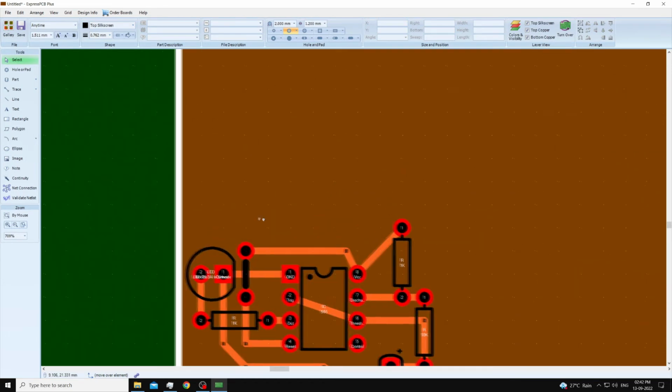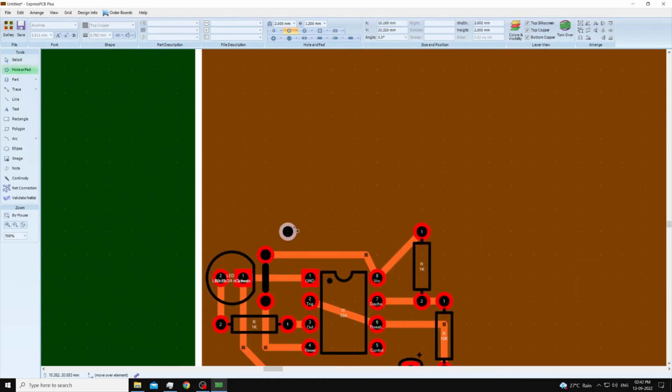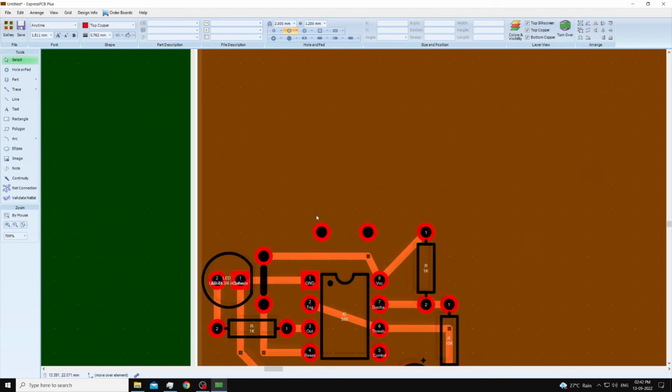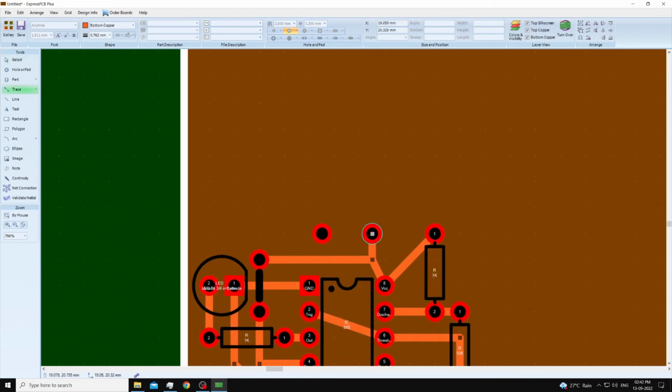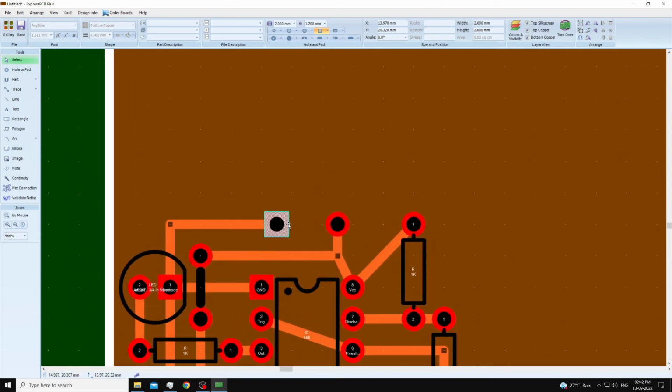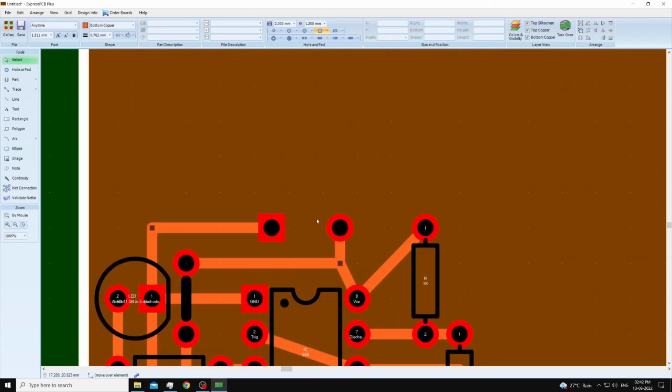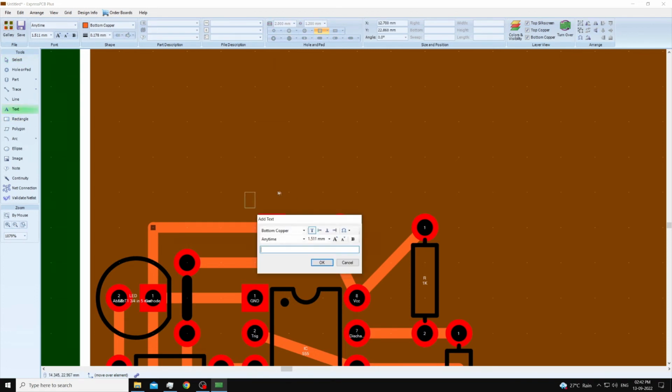I almost forgot, we need two more pins. The first is the power input and the second is the ground input. So basically these two pins will provide power to our entire PCB. So for the positive VCC, I just make a round hole, normal hole, and for the ground I will make a square hole. So just to identify those.